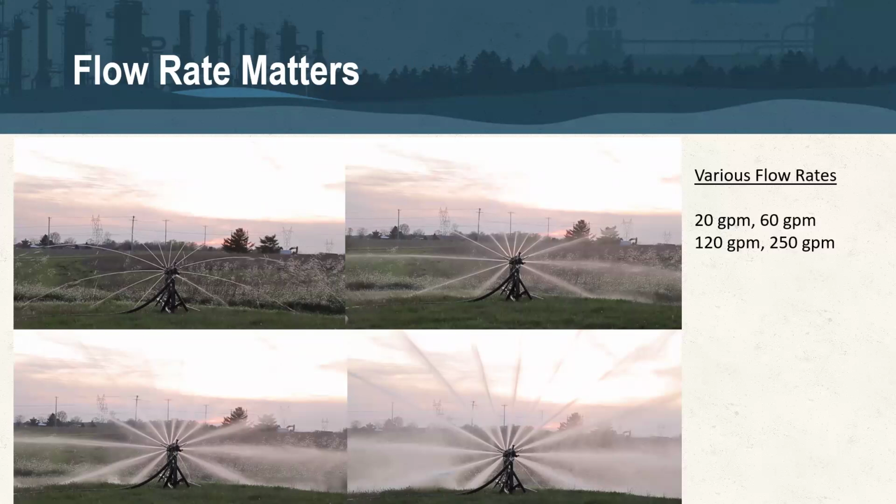And just to give you an example, when we're in shallower overburden settings, right, we may be trying to inject at a lower flow rate. When we move into deeper overburden settings or we move into transition zones like weathered rock, saprolite, and very much so when we move into weathered bedrock, we're talking about changing our flow rates and pressures to get distribution of this material.